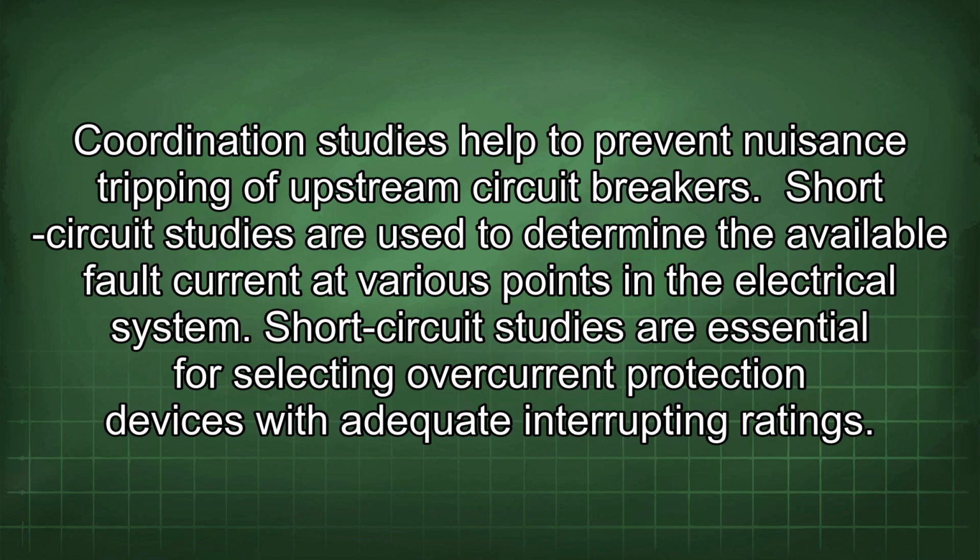Short circuit studies are used to determine the available fault current at various points in the electrical system. Short circuit studies are essential for selecting overcurrent protection devices with adequate interrupting ratings.